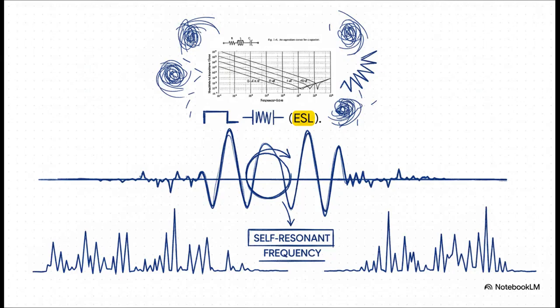And this right here shows you what's really going on. A real capacitor isn't perfect. It has a tiny bit of resistance, sure, but more importantly, it has that sneaky parasitic inductance we just met. At a certain high frequency, we call it self-resonant frequency, the good capacitor part and the bad inductor part basically cancel each other out. And at that point, it literally stops being a capacitor and starts acting like an inductor, the very thing that's causing the problem we're trying to solve.